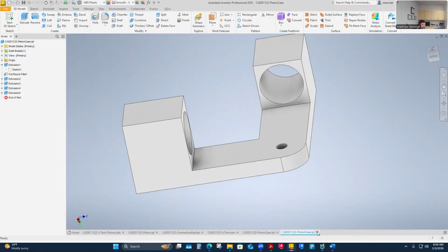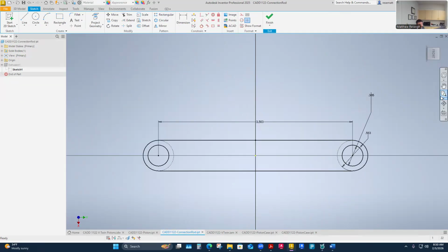Yes, going back to the connecting rod. Here it is. The only dimension I've actually changed from how I sized it all down was the through hole, to 10 thousandths over. Originally we were at 0.475, and I just multiplied that by 3/4.